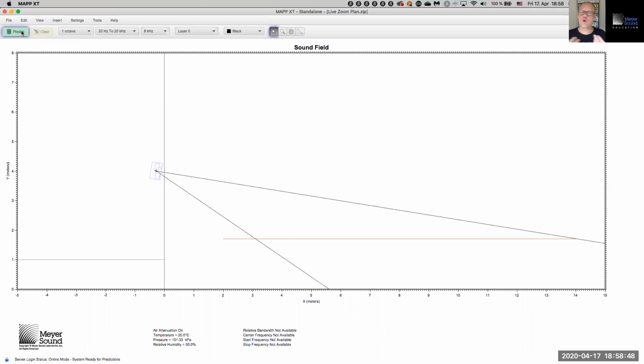Recommendation is look at those frequencies where the loudspeaker is steerable, where it's a point and shoot loudspeaker, not at low frequencies where most loudspeakers are virtually omnidirectional. So our recommendation is that you'll typically end up looking at a 1 octave wide interval, okay? It doesn't have to be 1 octave wide, it could be 1/3 octave, 1/6 octave, but in general, 1 octave is perfectly justifiable. And then there's several frequencies to choose from where this octave is centered, okay?